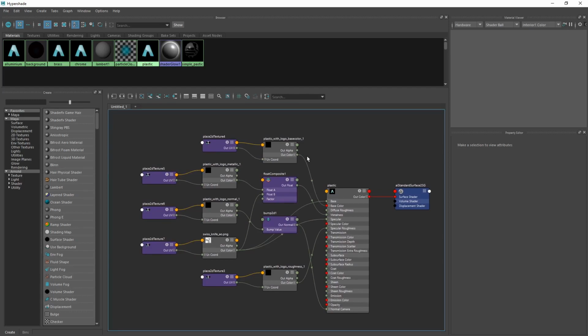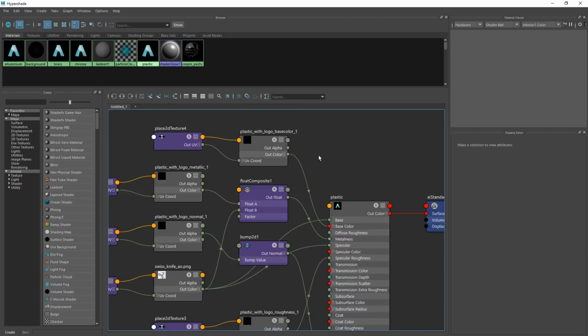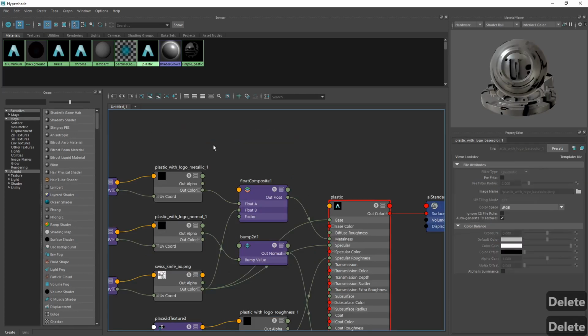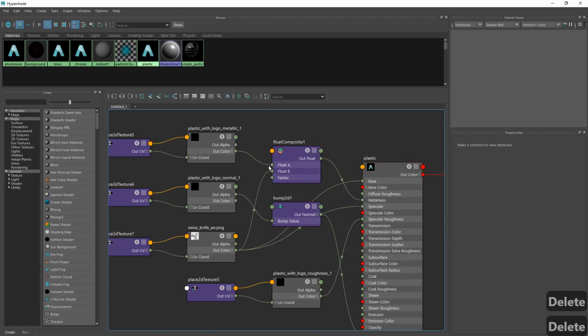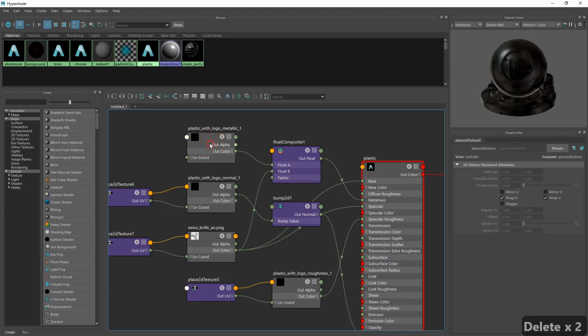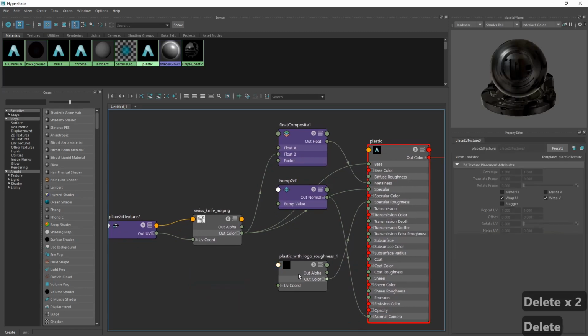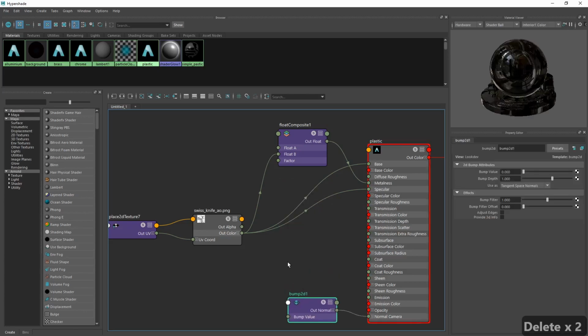First of all, let's delete all the old textures. Delete the base color texture, which we converted to JPEG. Also delete the metalness map, which we packed to a single texture. And the normal map, which we simply renamed. And finally the roughness texture, leaving only ambient occlusion texture, which we didn't touch.